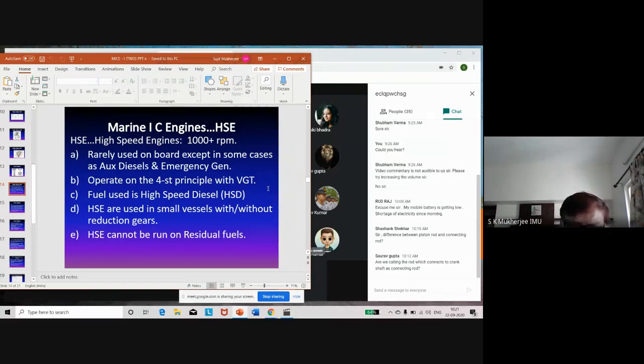Only the exhaust gases blowing on the turbine cause the turbine to rotate. And on that same shaft of the turbine, you have another blower, a fan. So the moment you blow exhaust gas on the turbine, obviously the blower will also rotate. And that blower will draw air and put it into the air inlet of the engine. So the air supply to the engine is coming through the turbocharger.